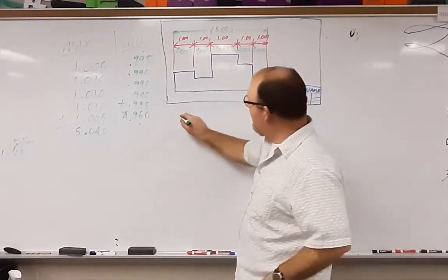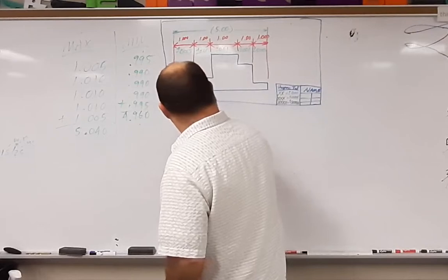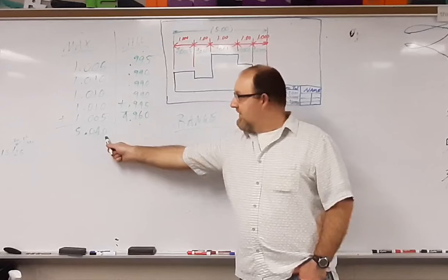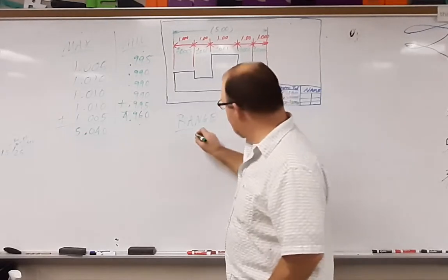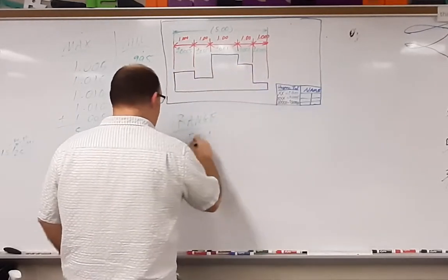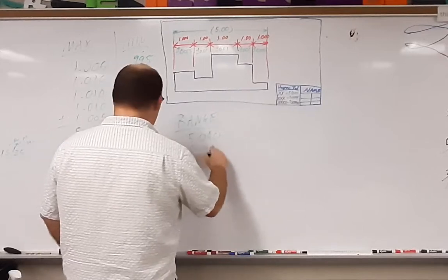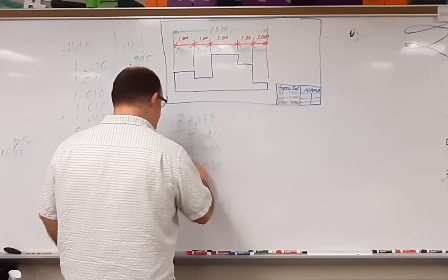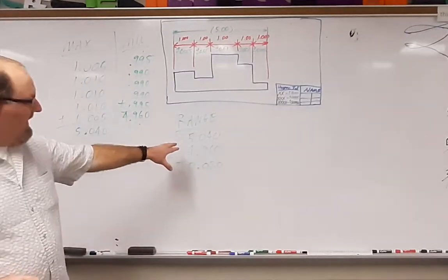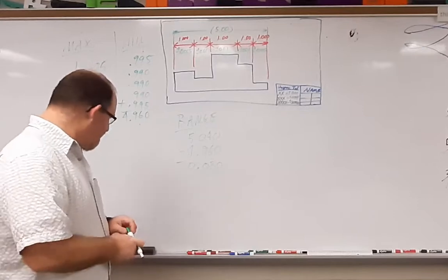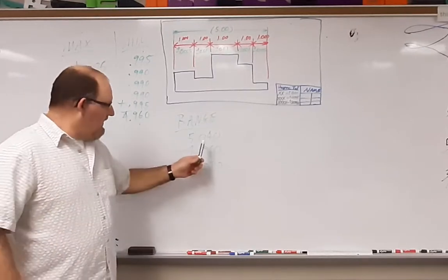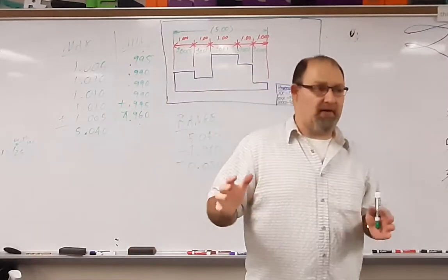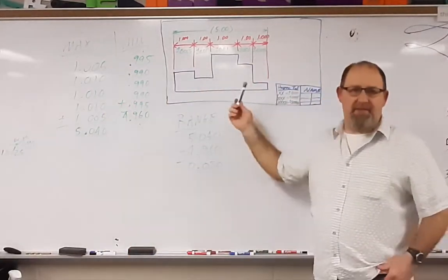So if we were to talk about our range, that overall range is that number minus that one. So 5.040 minus 4.960, which gives us 0.080. Okay? So with this here, we've now calculated the total tolerance range that part can be. This is one way of dimensioning.